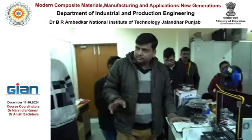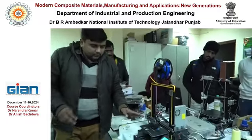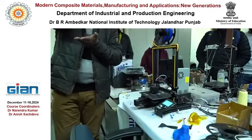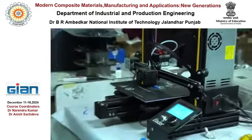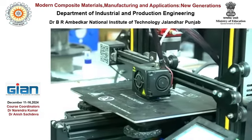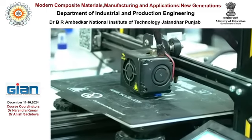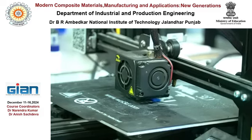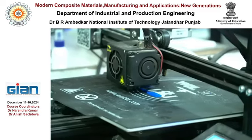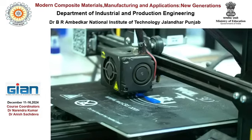Now just see, because we modeled this specimen there. Now what is happening here? The nozzle is depositing material layer by layer. Once one layer is completed, the nozzle lifts in the Z direction, toward positive Z. By how much distance? 0.1 mm, because the layer thickness is 0.1 mm. That's why we are not able to see it with the naked eye. We are not able to judge whether it is going in the upward or the downward direction.